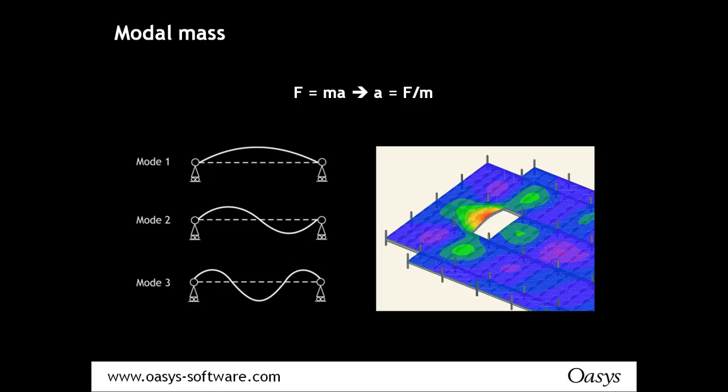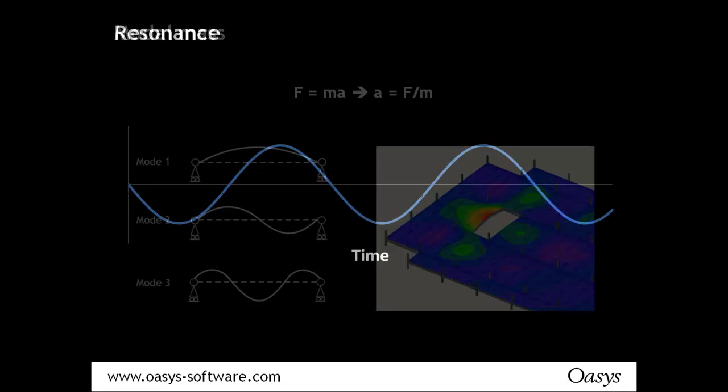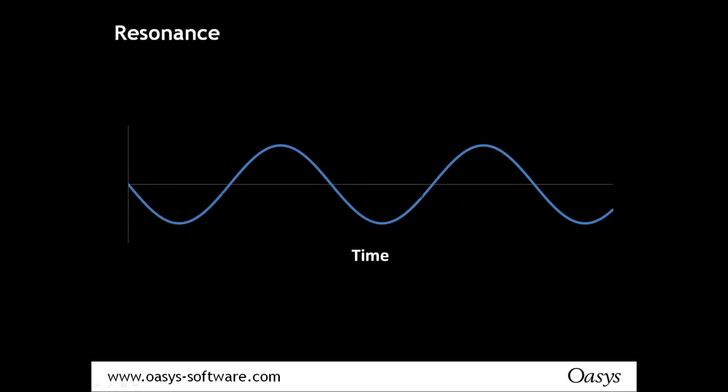Conversely, you do occasionally hear the fallacy that irregular bays do not have a vibration problem. That is unfortunately complete rubbish. The isolated bays tend to have the worst vibration problem. It's just that they're difficult to calculate without finite element analysis. We should look at that example later on.